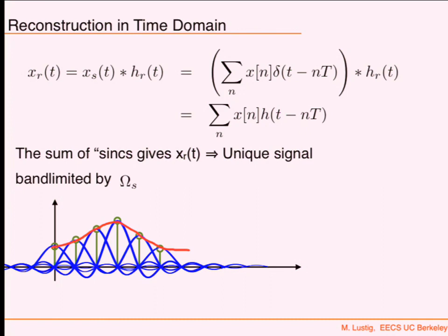And this is really the way that people in communications generate so-called almost band-limited signals, by convolving with something that has a really fast decay in the frequency domain. You can take a digital signal of plus and minus ones and convolve these impulses of plus and minus ones with a windowed sinc, and then you are guaranteed to have the frequency response of that windowed sinc. Okay, this is how these are generated.